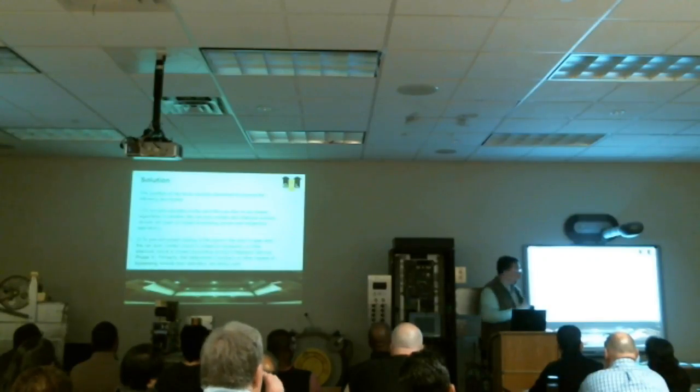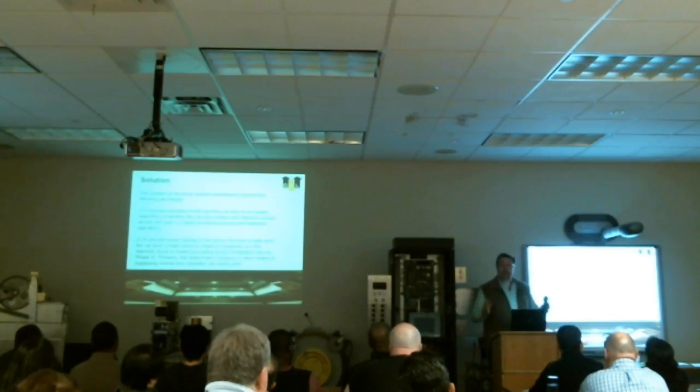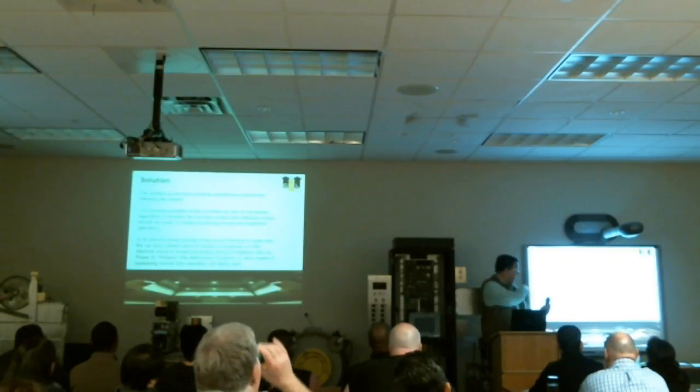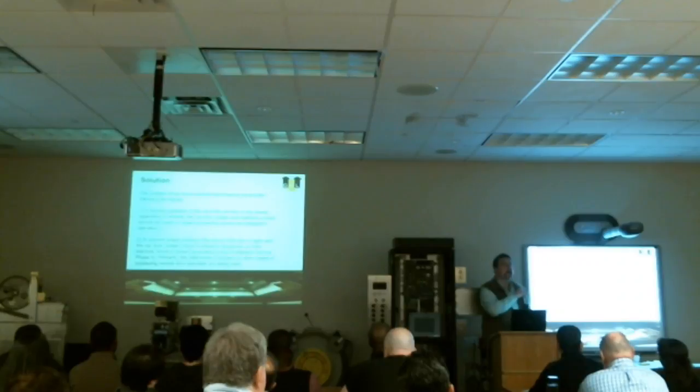The other portion of the code was to prevent the power closing of the doors if those contacts have been bypassed. So if somebody did leave a jumper bypassing the signals that tell us the doors are closed, even though the doors are open, we will prevent the elevator doors from closing and leaving the floor. Those are the two new code requirements instituted to prevent these accidents from occurring.